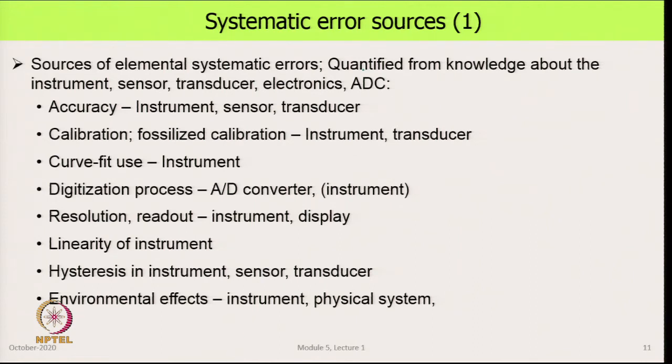So, we have to have knowledge about the instrument, sensor, transducer, electronics, A to D converter, everything else. And here are the various sources of systematic errors.